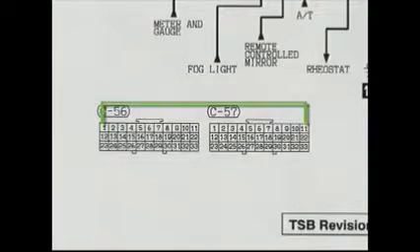Most repair manuals show the two halves of a junction block side by side. To determine which terminals align, you have to look at the layout as two facing pages of an open book. The terminals on the outer left and right edges go together, as do the terminals on the inner left and right sides of the pages.